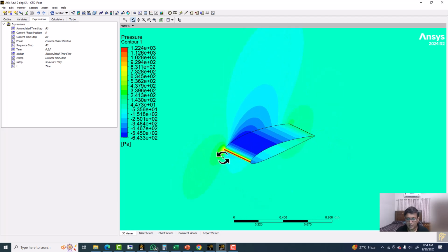So the overall area facing the wind is going to be equal to 1 into 0.3, so it's 0.3 meters squared. So why are we doing this? Because when we divide by the area, this will be a non-dimensional quantity, irrespective of both dimensions, the chord length and the span-wise direction. So it is independent of these values.